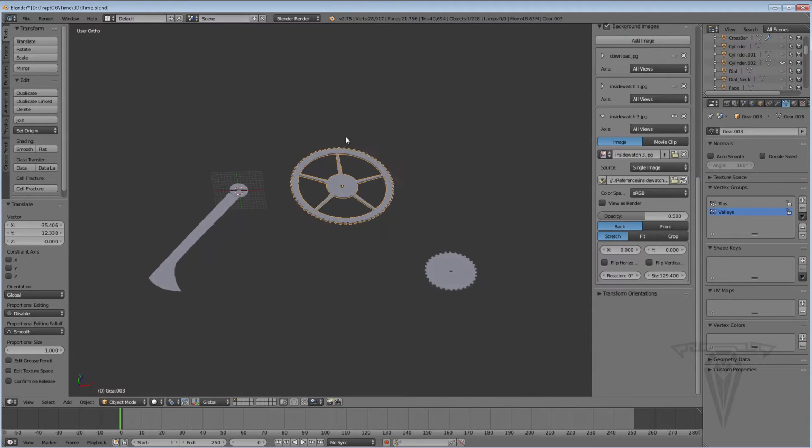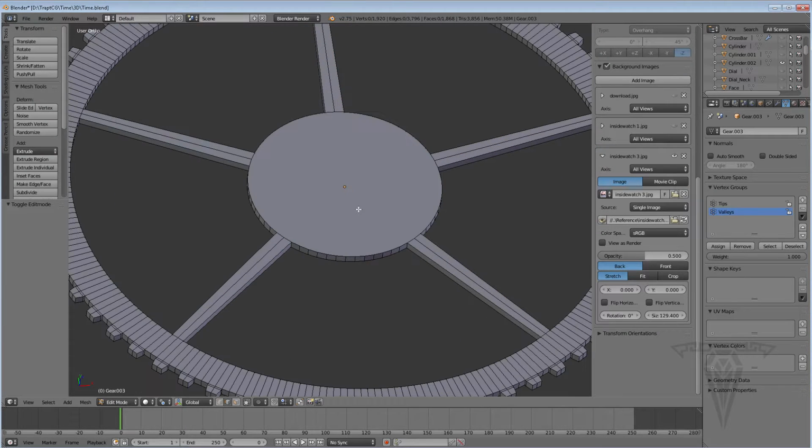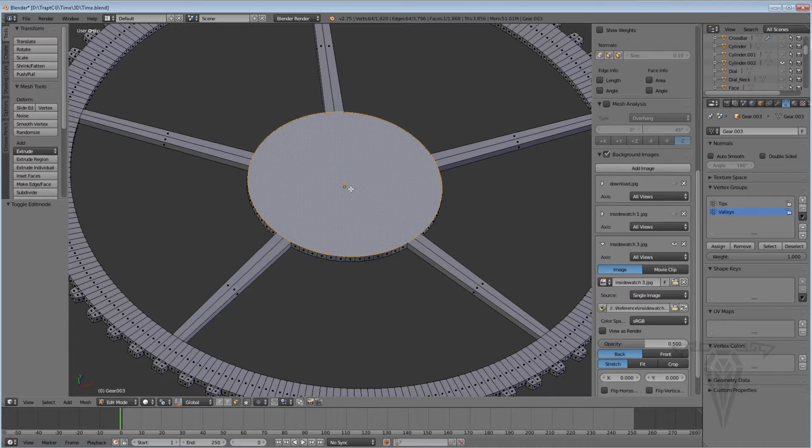So if I go into edit mode, let's see, sorry, Tab on the keyboard. I'm going to select this face here, so go to face mode. And I can inset, I on the keyboard to inset, bring it down. Oops, I'm going to undo that. Select the face, I'm going to make sure my mouse is way out here.